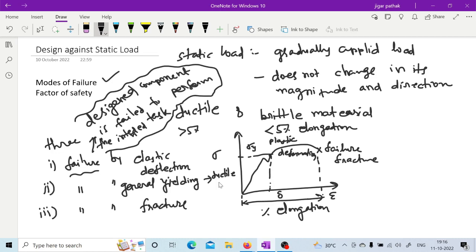Did you get it? Okay, so you don't need to take it up to the yield point before it can be considered as failure. See, if the permanent deformation will remain, in that case we can consider it as failure, right? Otherwise, if that deformation is not taking place, then we cannot consider it as failure, because without deformation it may be able to perform its intended task.